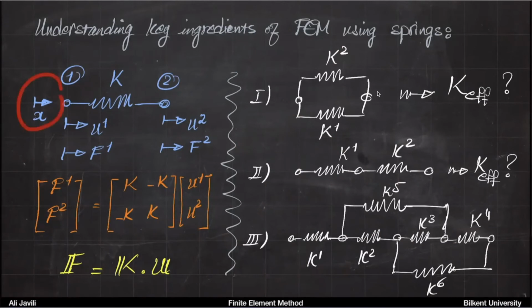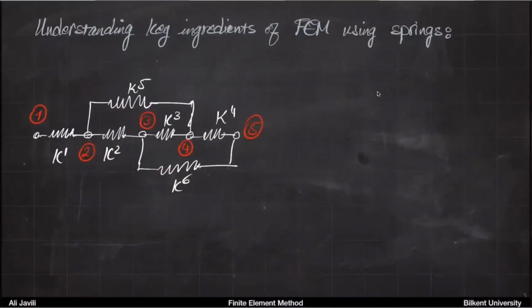If you were in a 2-dimensional space, then for 5 nodes, you get a stiffness of the size 10 by 10. If you go for 5 nodes to a 3-dimensional problem, you get 15 by 15 for the stiffness. Okay, so the size of the stiffness matrix is always something like number of nodes times problem dimension, times the same thing, obviously. So before you do anything, it's going to be a square matrix. So it's number of nodes times problem dimension.